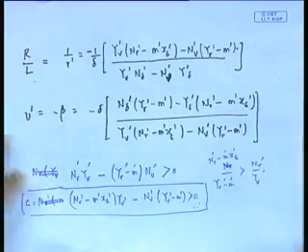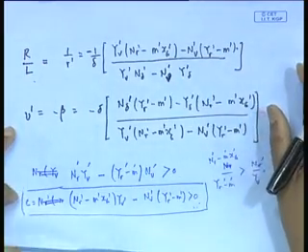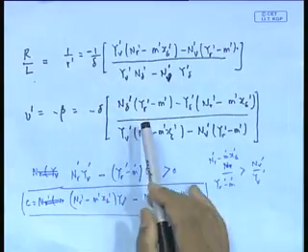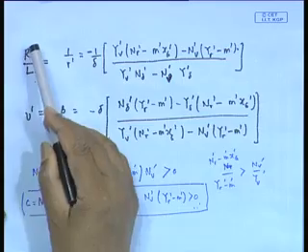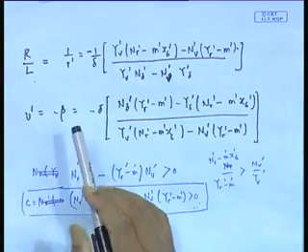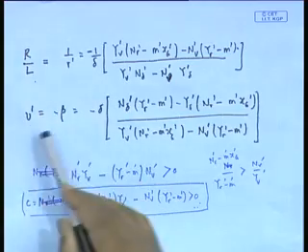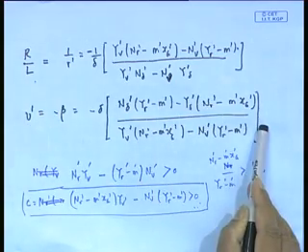Okay, we will continue our discussion on the turning maneuver. I will bring back the last slide of my last lecture. What I was trying to mention is that in the last class we found out that in a turning maneuver, R by L, where R is the steady turning radius and L is of course the ship length, is given by this expression, and the drift angle minus beta is given by this expression.